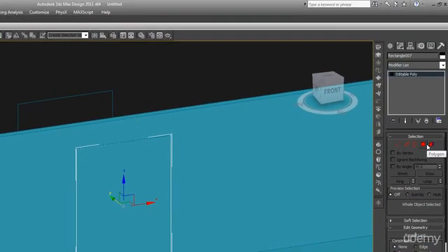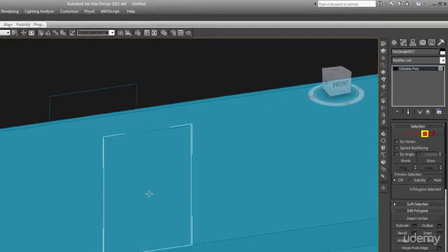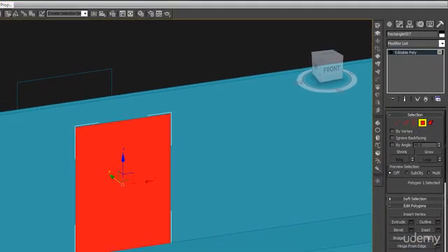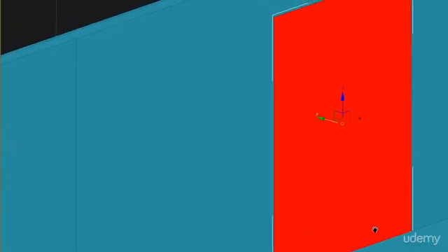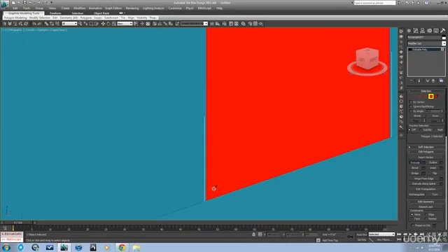Now here's some edit poly stuff. Let's take this face. Select this face, this polygon. We're in polygon subobject mode, and we'll create kind of the molding around the door. I'm going to show you a bunch of poly tools here that we'll be able to use later too. So extrude is one of them. You can extrude just this face here. And these are all inside the modifier of this particular edit poly. In face mode you can extrude. So let me just show you what you can do. You can just click there and push that face out a little bit like that.